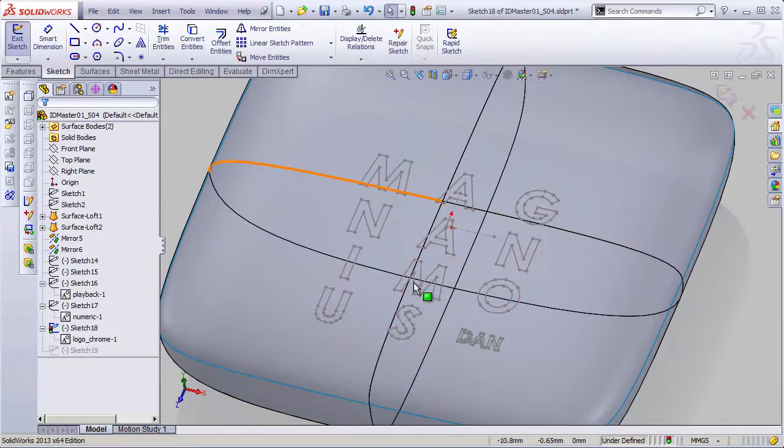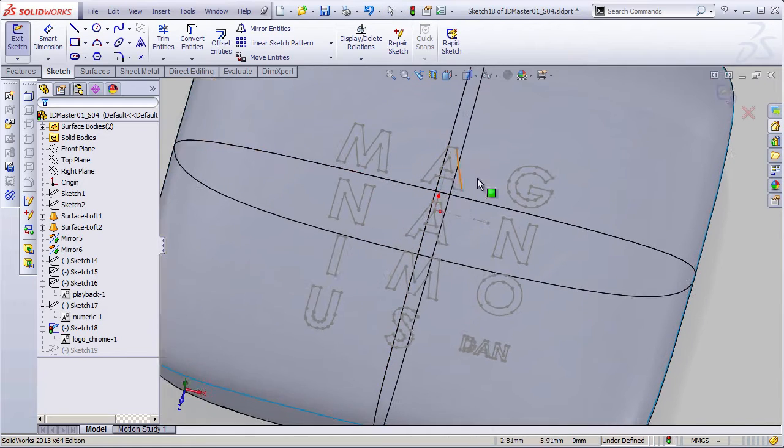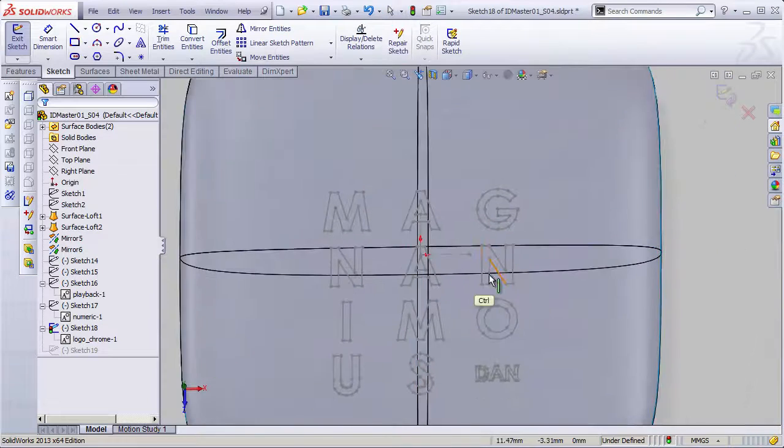It's a way of grouping together geometry that goes together and that we don't accidentally want to change in any way, like a logo. Blocks are really powerful. They're really important. You can copy and paste blocks. You can reuse blocks. You can scale blocks, rotate blocks. They're great. But we need to be able to mirror this, and that's something that's not built into blocks. We have to do it a little bit, well, in a roundabout way.